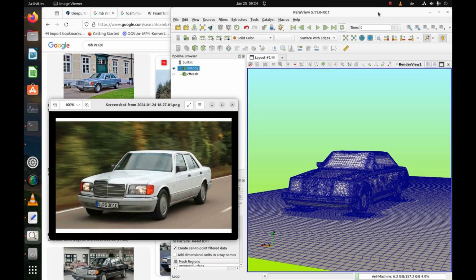We investigated the behavior of the snappyHexMesh tool by running it with different mesh quality control settings. We compared 2 tools, Snappy and cfMesh, and found out that cfMesh is easier to operate, but Snappy has more options for controlling the mesh quality or layer creation process.